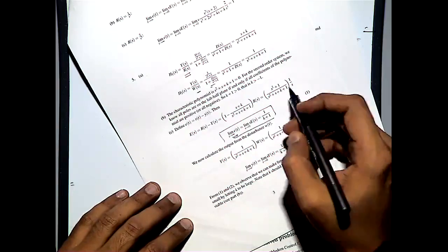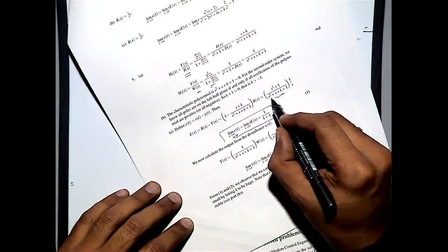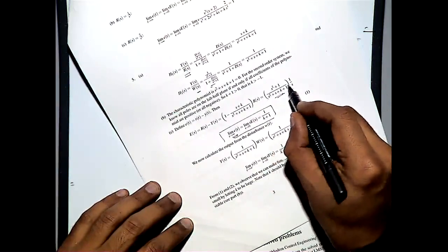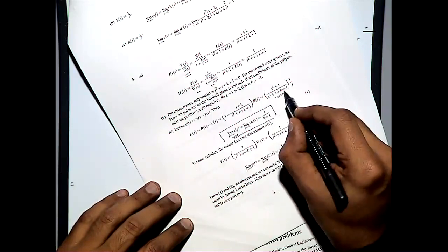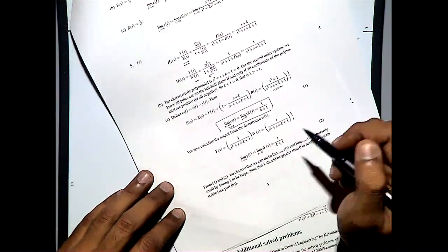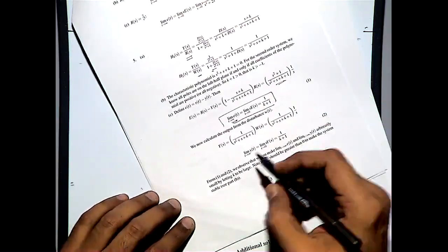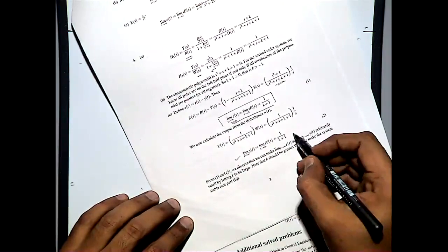Before doing so, you need to check whether the system is stable for that value of k. In this case, it turns out that you will get a quadratic equation. So all you need to look at is whether you have constant positive coefficients for the polynomial. Similarly, you can also find out the steady state value of the output to a step input.